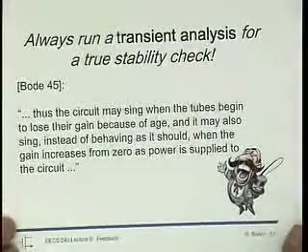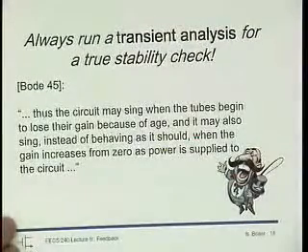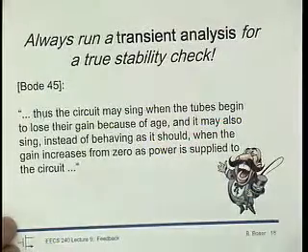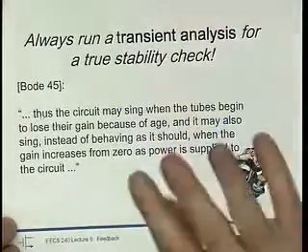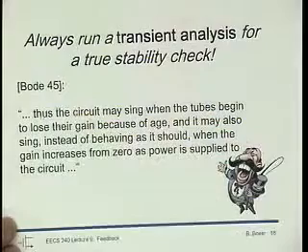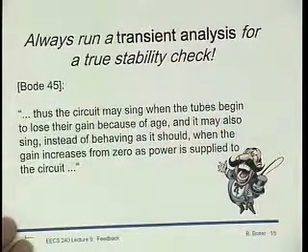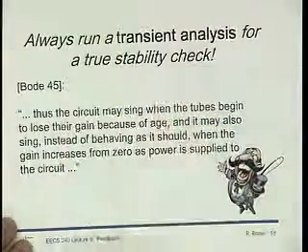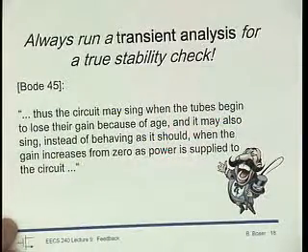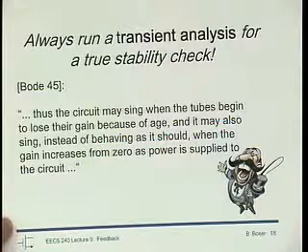Okay. So likewise, test stability by putting in big stimuli, small stimuli, square waves, sinusoids. So it's great, right? We have fast computers, so we can try lots of things. But ultimately, it's kind of these crutches that make sure that we haven't forgot anything. If you really want to be careful, then go and figure out bad things that can happen.